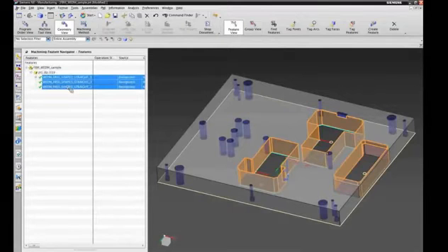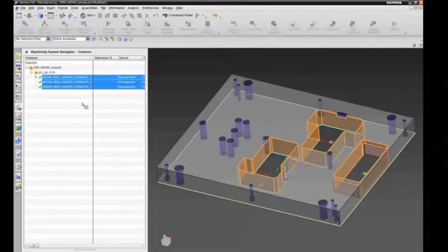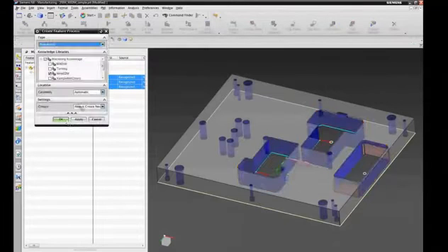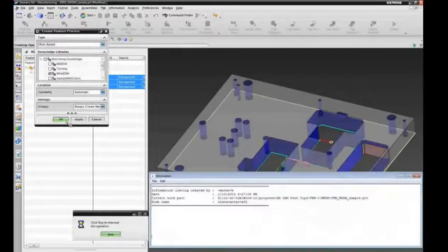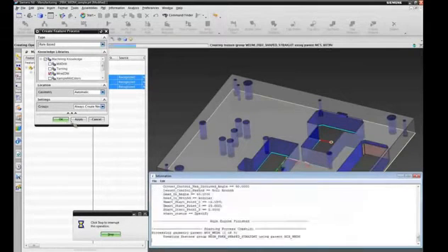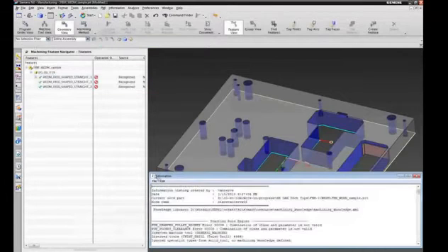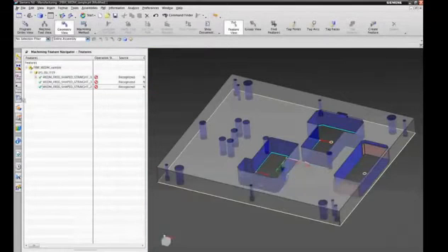Let me just rerun the process with a small change in the machining knowledge editor. Running it again. Now, if everything works as I hope, I shouldn't see the internal trim operation anymore, but I should see a no-core operation. So let's see if that worked.